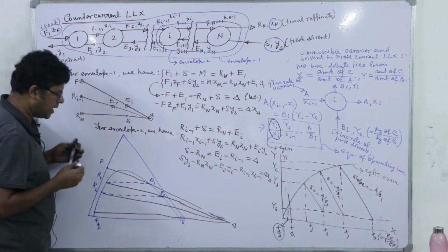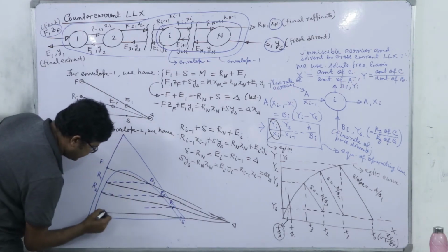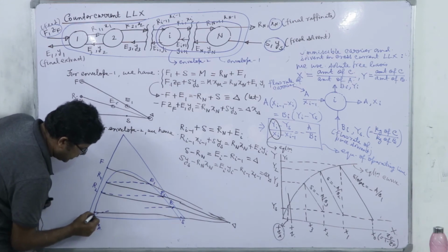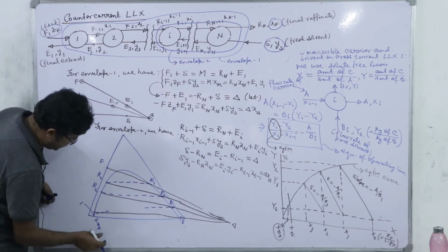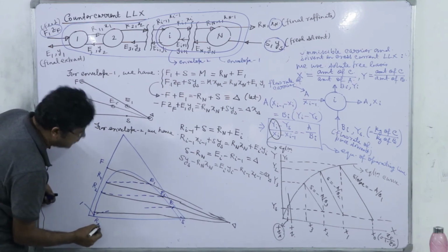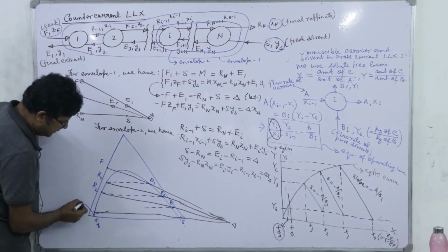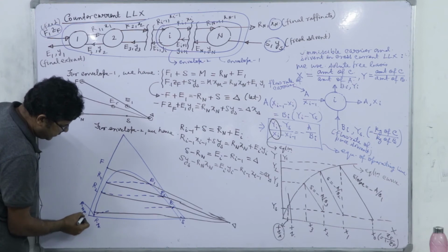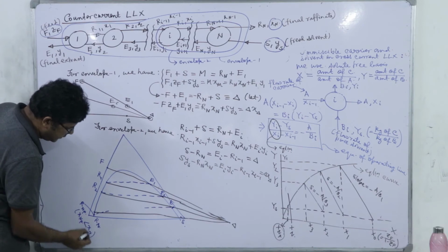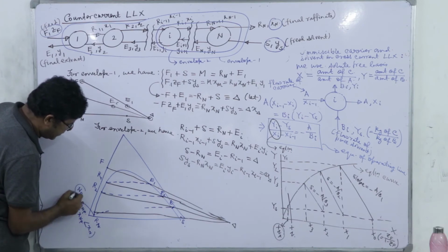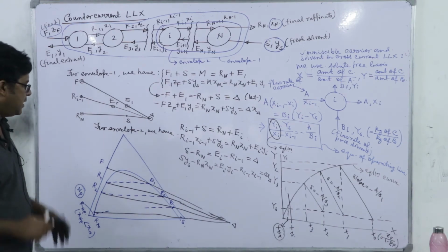So in this way we will continue, this is E3 and again the tie line, and we will continue until we get a tie line going below this point Rn, because we haven't used RNP, it is Rn, right? And let us say this is RNP where XNP is lower than Xn. So NP is the number of stages necessary to achieve this specific requirement.